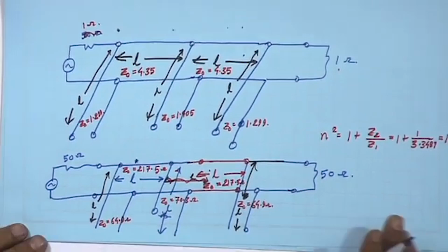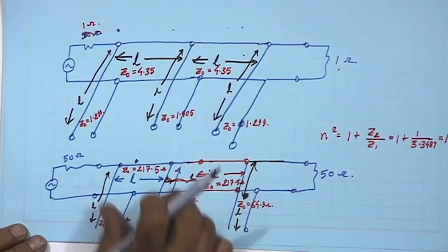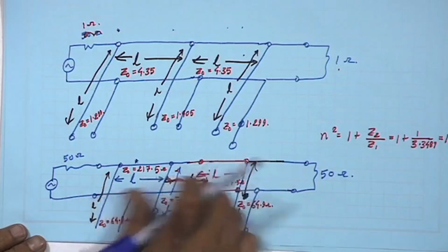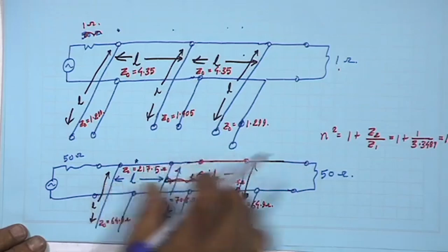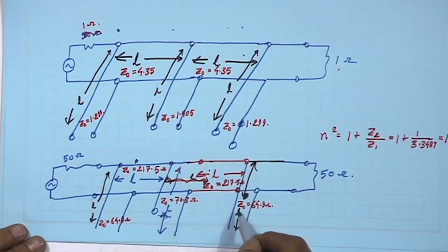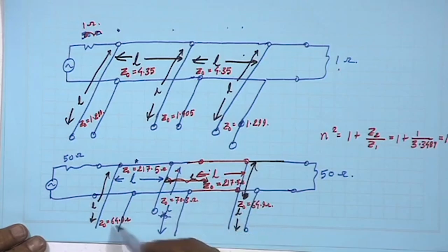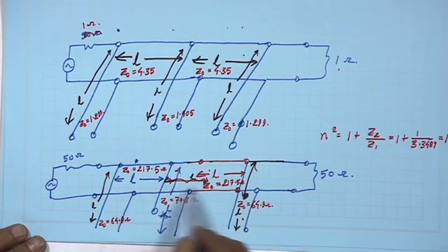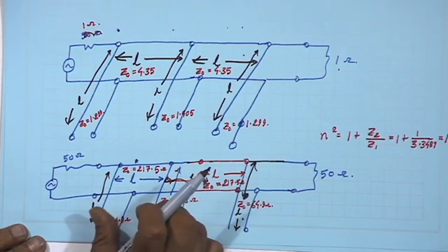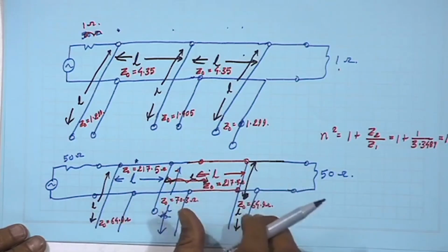Okay. So, you see I now have these 3 stubs, and also 2 unit cells, but they are not stubs, they are transmission lines. These 3 are open circuited stubs. This is for the first inductance, this is for the capacitance, this is for the inductance L3, and these are unit cells. So, now with these lengths the sizes are manageable.